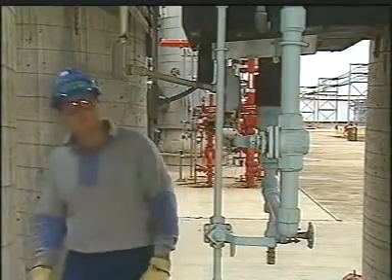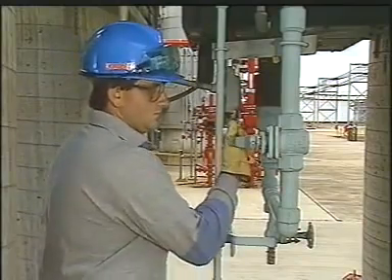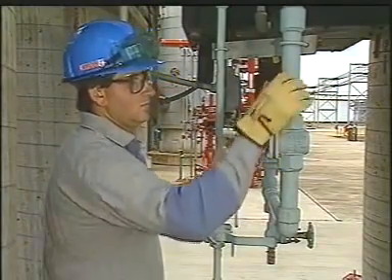As always, during shutdown and startup, workers must follow safety precautions. Nitrogen and other inert gases are used to purge the exchanger of hydrocarbons and air. These gases can get trapped inside the exchanger where they interfere with the heat transfer process. These gases can be released by venting according to the procedure specific to your unit.